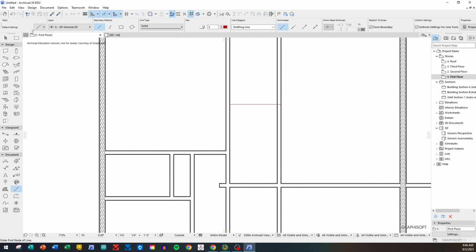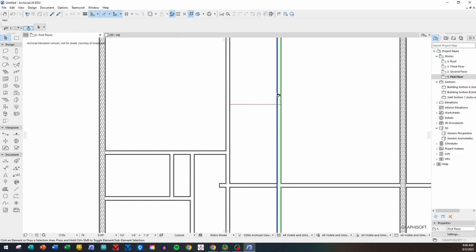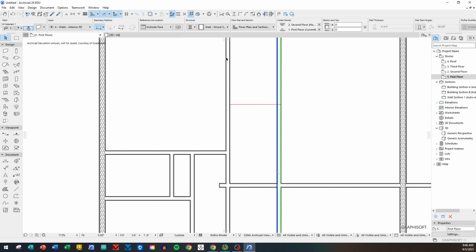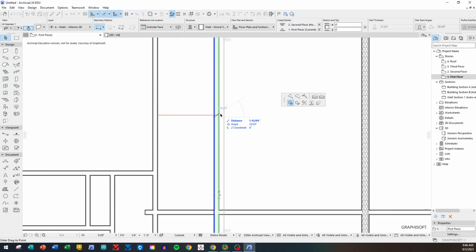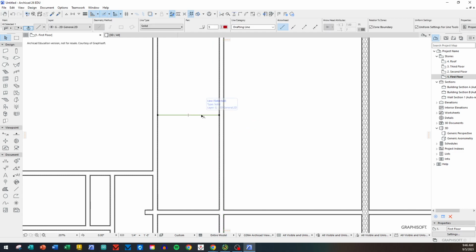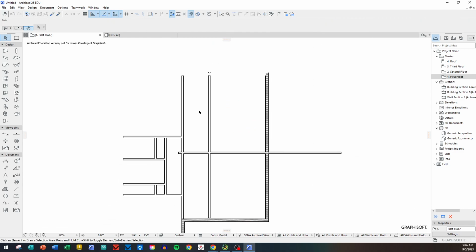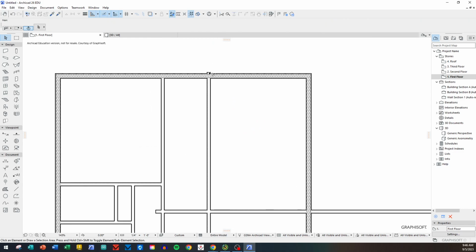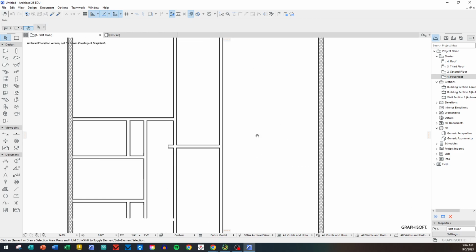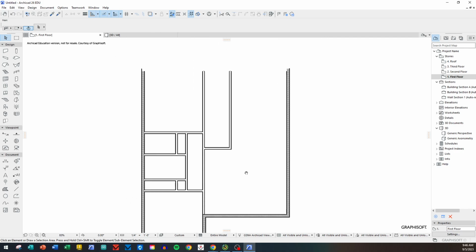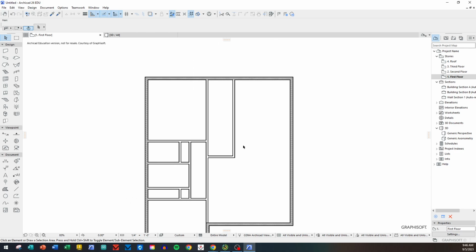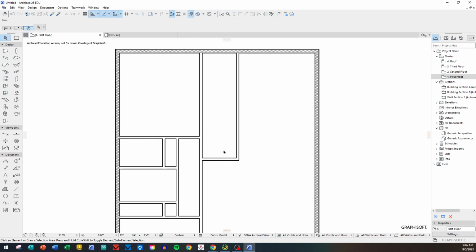Got it. And then if I go like this and I move that wall right there to the end point, that means it's exactly 5 feet across there for that bath. It doesn't mean that wall sticks to the back side. I can use my control key and just click on it to trim it off, just like the rest of it. Now what you're going to notice in some cases is that the kitchen stem wall right here that covers up the side of the fridge and stuff, I'll worry about that later.